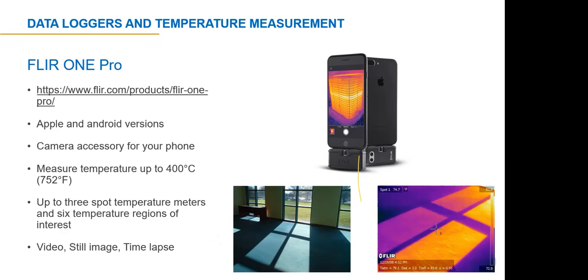IR cameras need to be used properly. Do not take a picture of the window itself. Take a picture of the space inside the window, either the furniture or the floor. The space inside will be cooler, whereas the actual glass will be hotter with film.